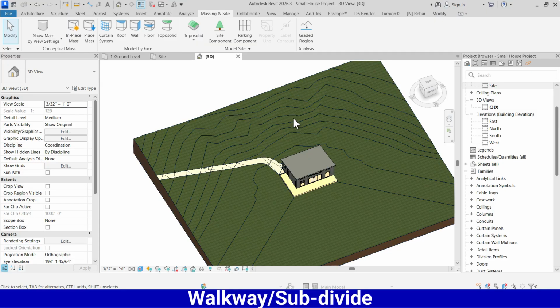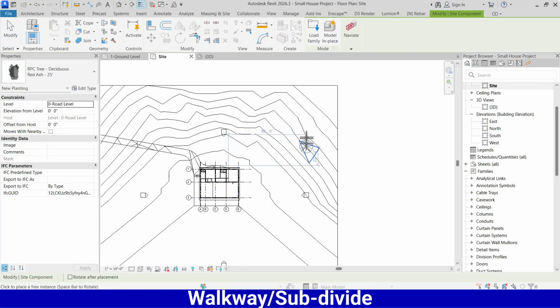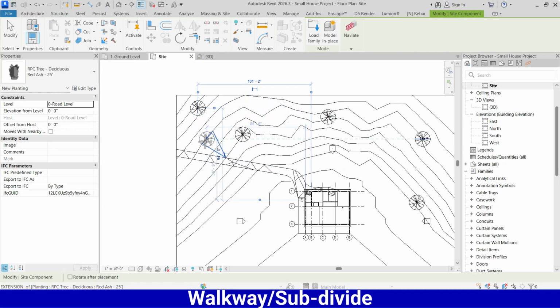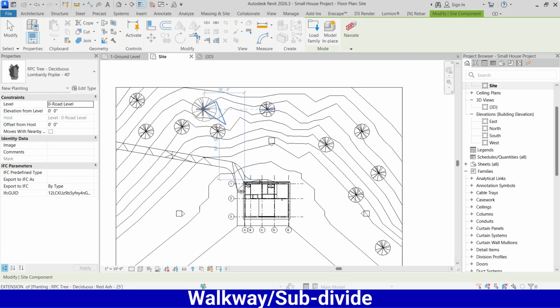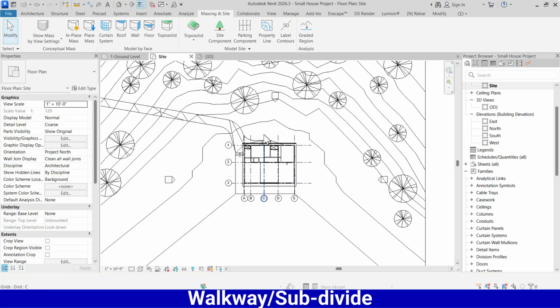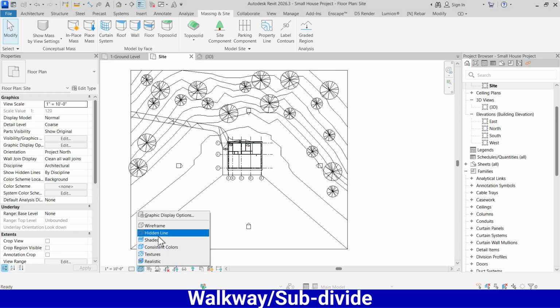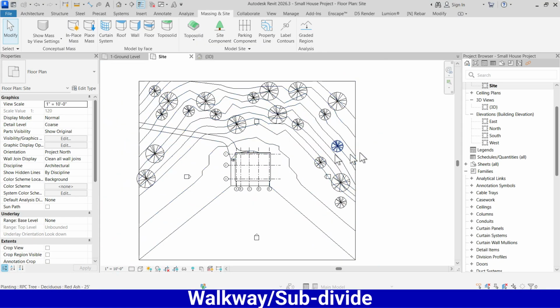Now if you want to add some more elements, go to site and site component, select it and add the trees, like this, a bigger size here, here, here also. It's so simple. Make it hidden and you can see our topography is ready. It's looking really nice.